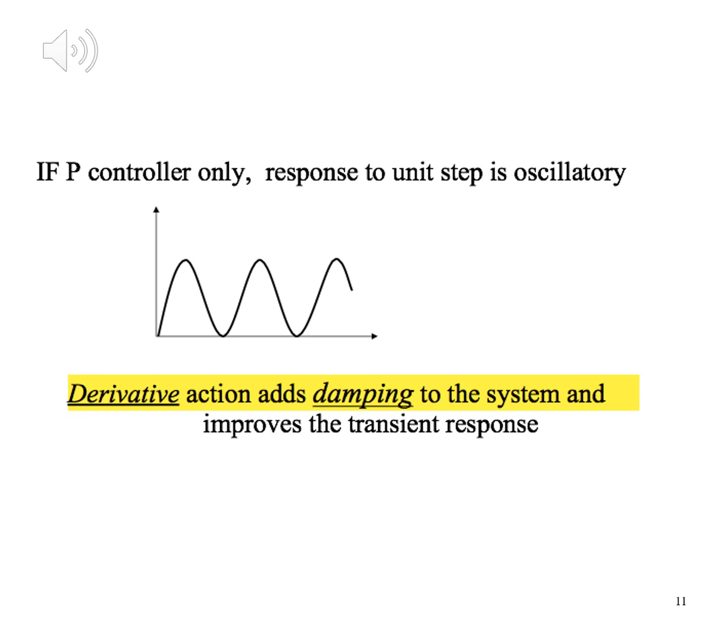Therefore, you decrease the complexity of the system due to your design. So when you are asked to design, if the question is design a suitable compensator without specifying which kind of compensator, you have to search for the best design, the optimal design, not just put a PID controller.